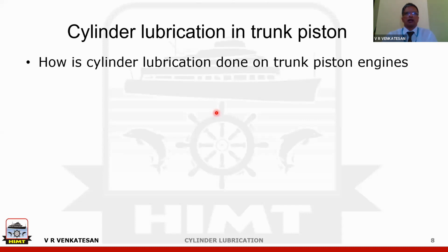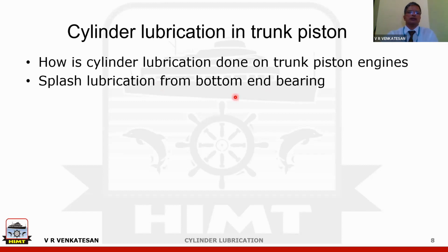So what do you mean by splash? It is not that the connecting rod will hit any oil or anything. It's not like there is a stagnant amount of oil in the sump, and then the moving connecting rod will touch that, and that is how it will splash. So what do you mean by splash? It is oil coming out of the bottom end bearing. From the bottom end bearing, lube oil will escape.